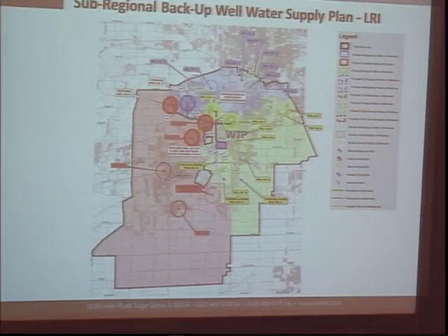From that spine, we're suggesting coming north to pick up a future Village of Montgomery well. It would be well number 17. You have a site located along Dixon Road or in the subdivision along Dixon Road where well number 17 can be drilled. Would also come up 14 and 15. Those are existing wells. You already have the raw water main in between those 2 wells, so you just have to tie in to that water main to bring those back.